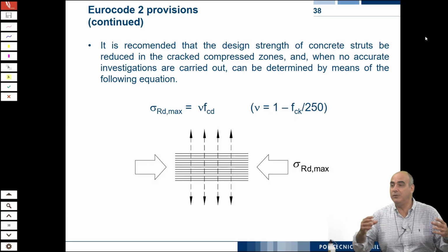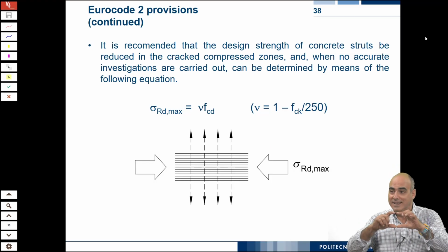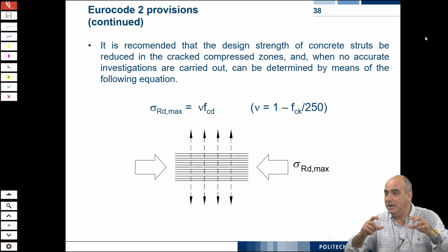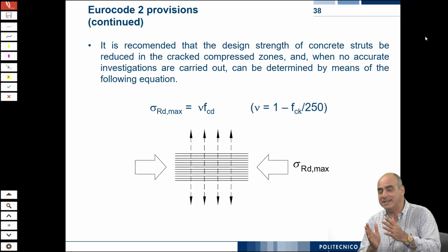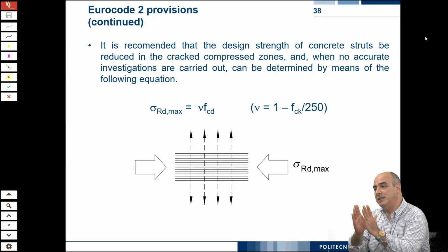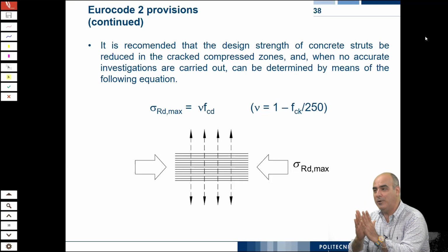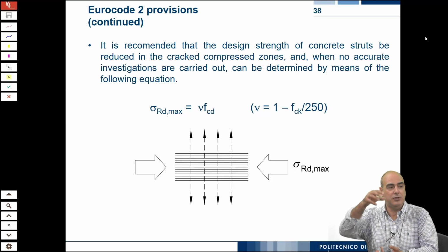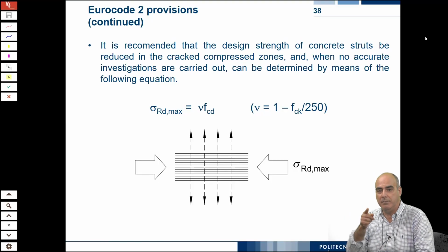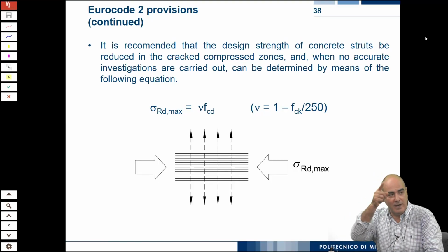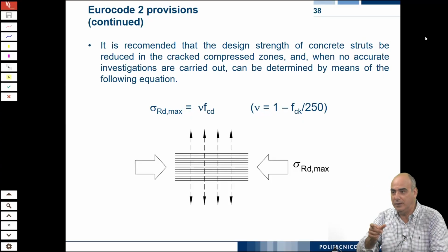Also consider that if you have a higher strength concrete, the sides of your strut can be smaller because you need less material to carry that strength. Also, if you have cracks, the solid part between the cracks, if it's very narrow and slender, can undergo some kind of local buckling. There is a theory to interpret the failure of a cylinder under compression that says at a certain point, you have formed internal cracks which are vertical, parallel to the strut.